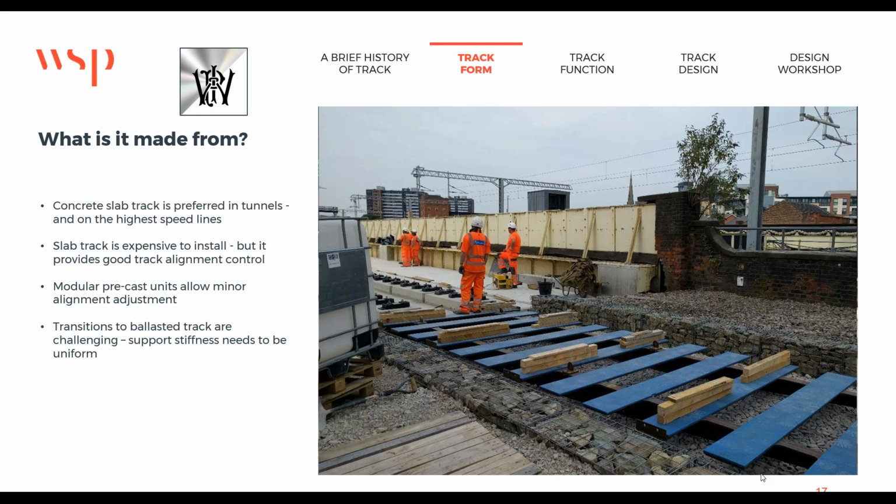That's never a truer statement than the one you related. Twist faults will derail a train irrespective of speed. The only thing the speed component does in a twist fault is determine how much carnage there is once the train's off. So if you derail on a twist fault at slow speed, bump, bump, stop.